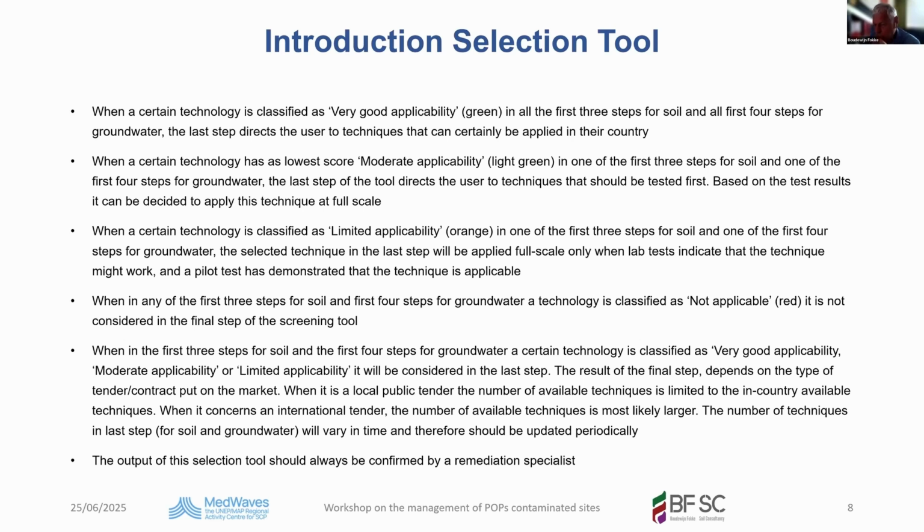But as soil remediation is not that deep as you need for oil drilling, we have mechanical drilling rigs which are smaller and more mobile than the drilling rigs used for oil drilling. That's number one. And of course, the techniques for cleaning, especially oil contamination, is limited to bioremediation, depending on the concentration.